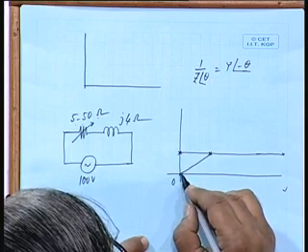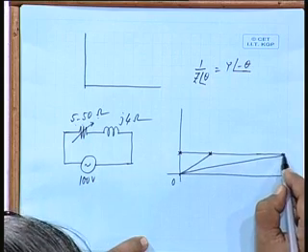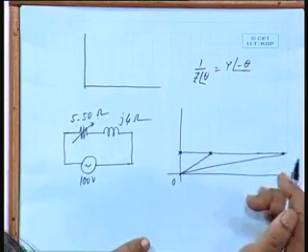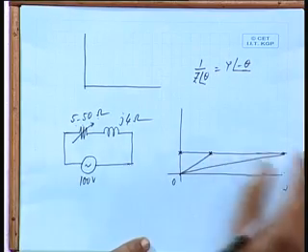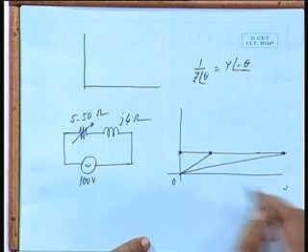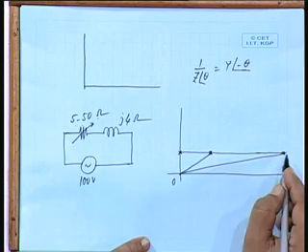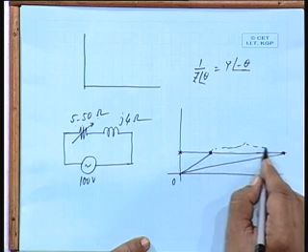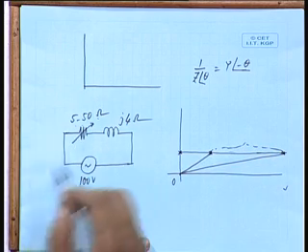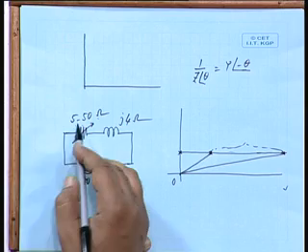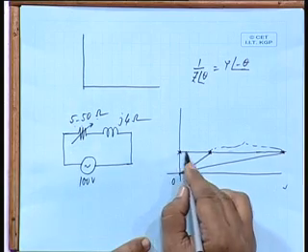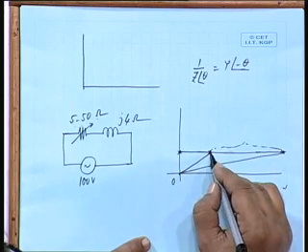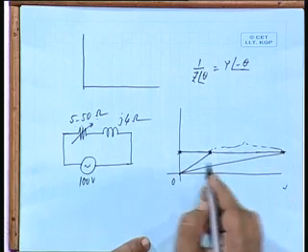Similarly, 50 ohms down the line here, somewhere here say. So, 50 ohms has to be chosen to scale. We are not really following any scale here, it has to be drawn on a graph sheet with scale. So, this is 5 plus j4, this is 50 plus j4. This is the portion of our interest. Had it been from 0 to 50, then this would have been the corresponding segment, is it not? So, we are interested in the inverse of this portion.